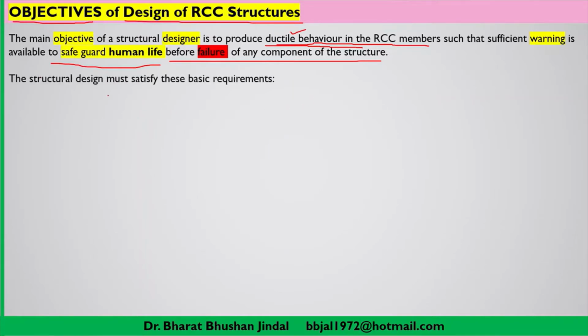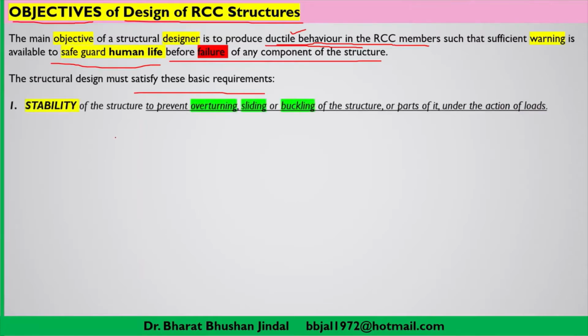Now, structure design must satisfy some basic requirements. Very first is stability. Your structure must be stable. Stable means any type of overturning, sliding, or buckling of the structure or any part of it under the action of load should be prevented. Otherwise, its stability will be lost and a failure can occur.